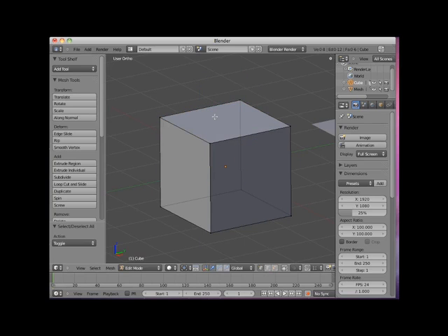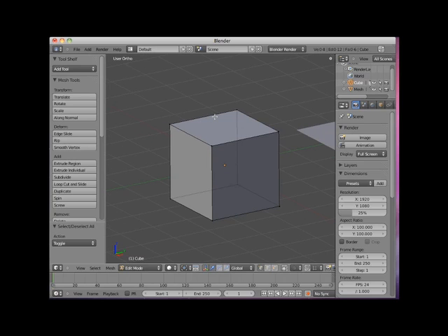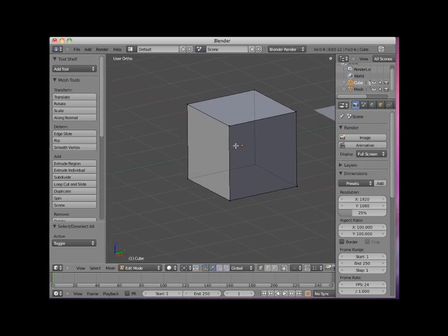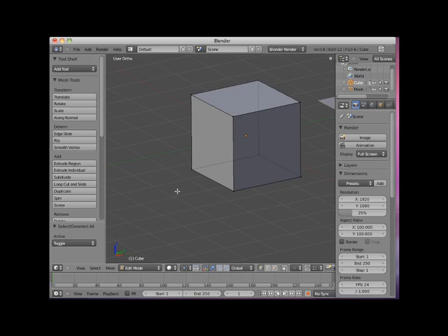Although Blender has no single vertex primitive mesh object, it is possible to create a vertex by simply holding down your Control key and left-clicking on the 3D display. Here I will create a single vertex. With the new vertex still selected, I can continue to hold down my Control key and create additional vertices with connecting edges with each mouse click.